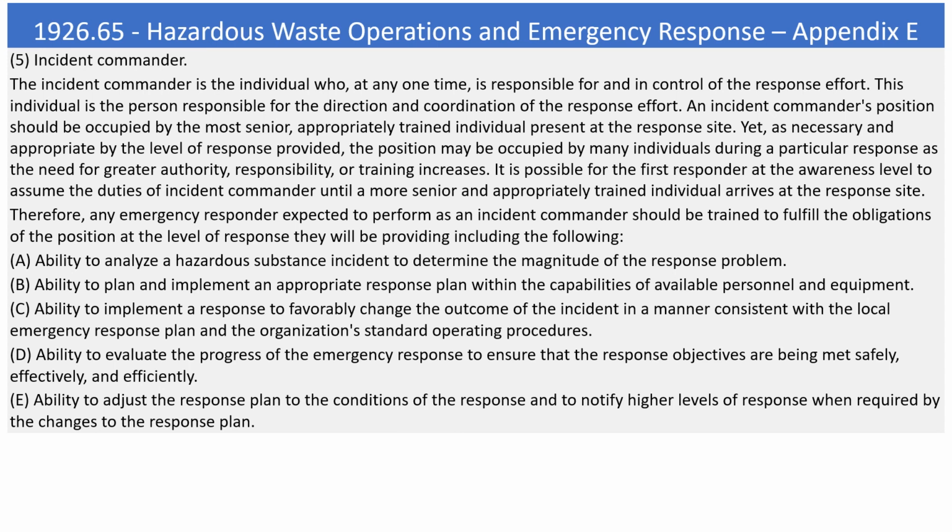Ability to analyze a hazardous substance incident to determine the magnitude of the response problem. B. Ability to plan and implement an appropriate response plan within the capabilities of available personnel and equipment. C. Ability to implement a response to favorably change the outcome of the incident in a manner consistent with the local emergency response plan and the organization's standard operating procedures. D. Ability to evaluate the progress of the emergency response to ensure that the response objectives are being met safely, effectively, and efficiently. E. Ability to adjust the response plan to the conditions of the response and to notify higher levels of response when required by the changes to the response plan.